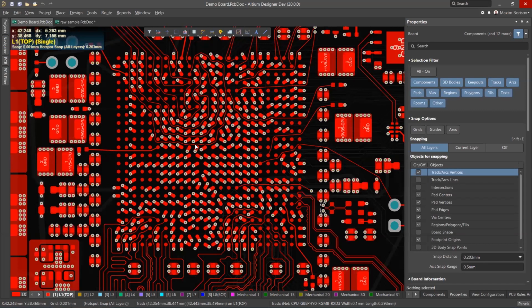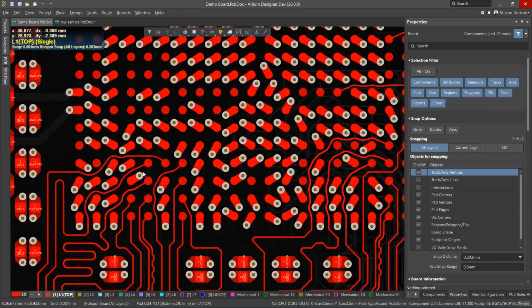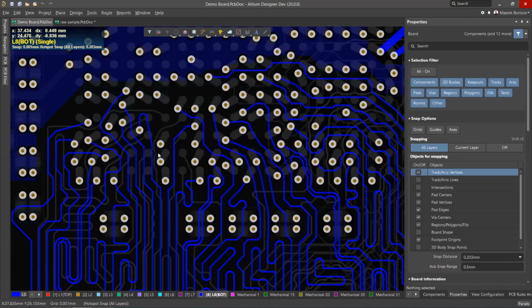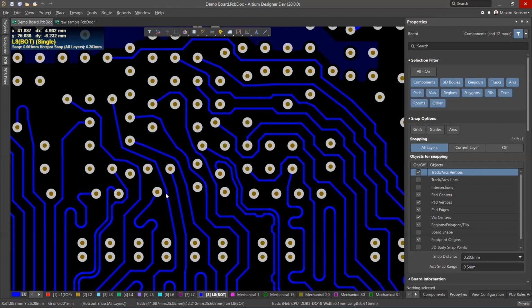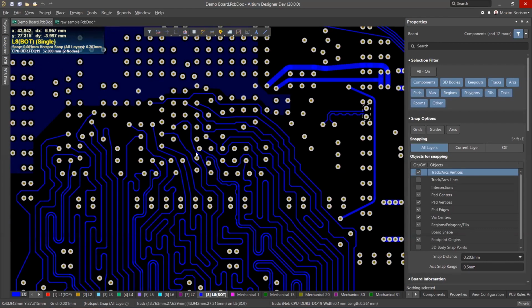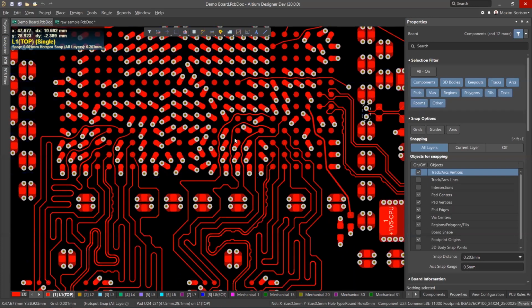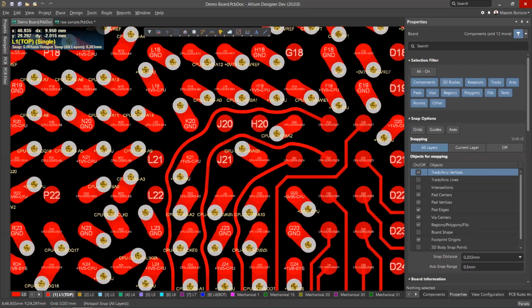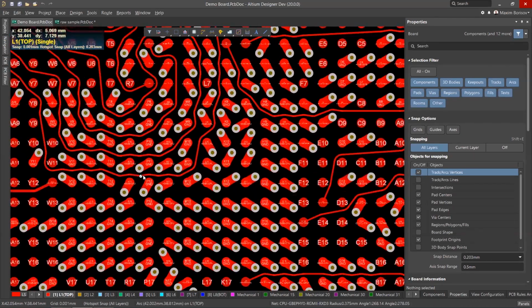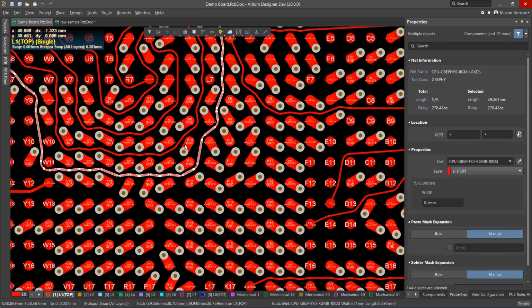It's very useful for high-speed designs. Here I have a setup with odd angle segments and arcs. And when you use this new router, it's possible not just to keep everything better grouped, for example keeping byte lanes on their corresponding layers, but also with this very important property where we have the shortest possible path.